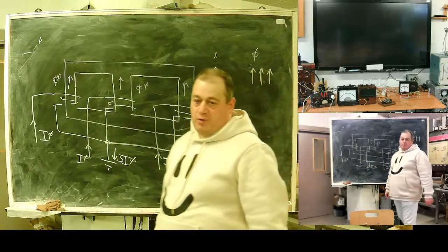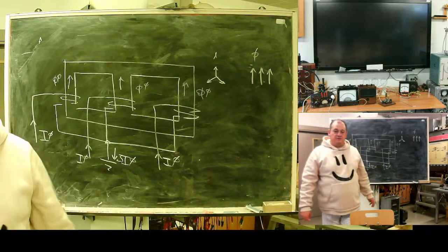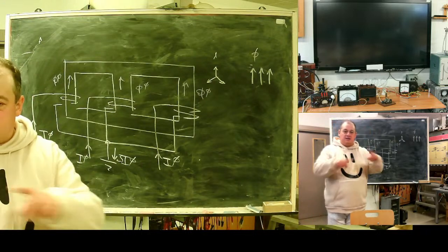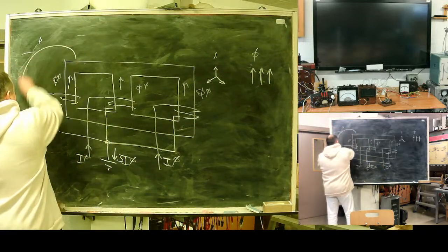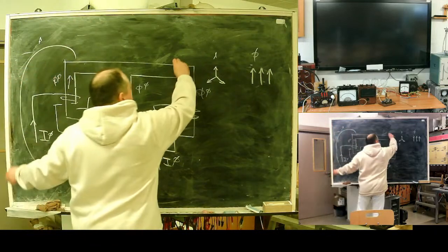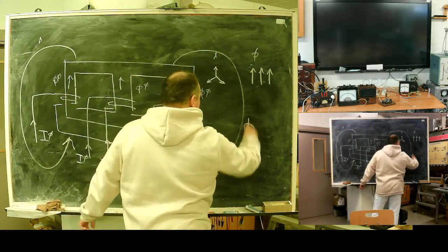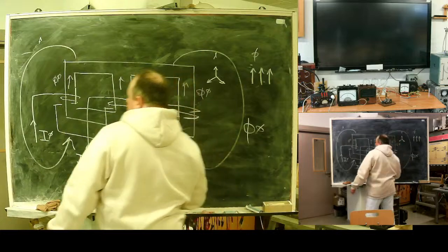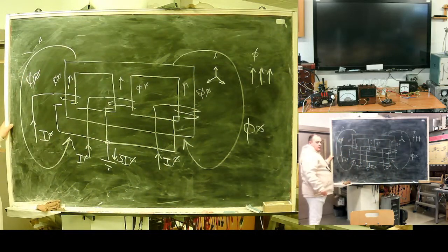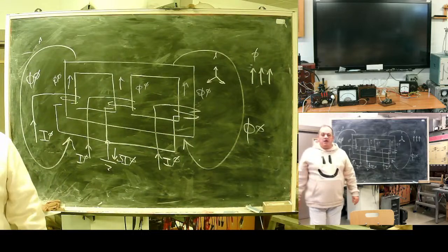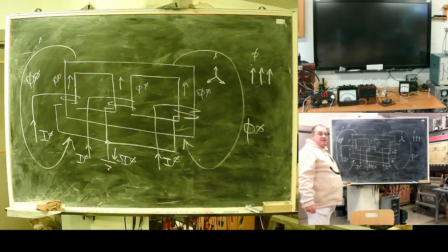Some will be triple, and we have a situation where three cars want to cross one intersection simultaneously. No way. Zero sequence flux can close only through air. Only by air. In theory, such a transformer should have zero reactance.